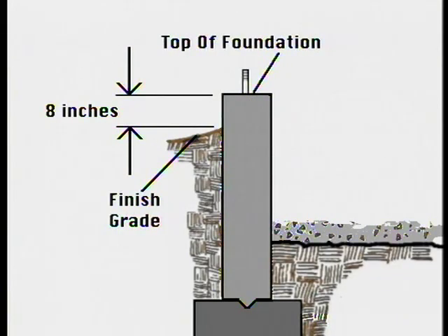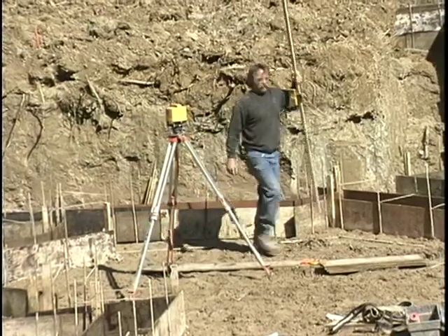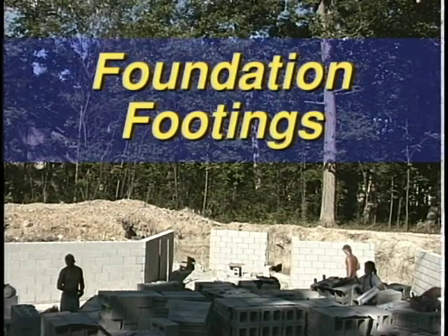Foundations should extend about 8 inches above the finished grade to protect wood members from moisture. A laser system can again be used to check the height of the foundation wall.